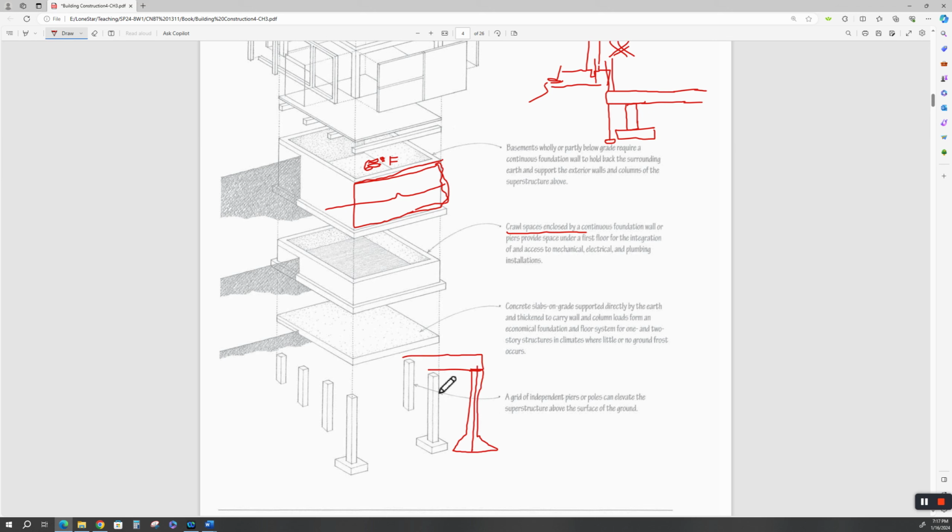They usually use crush boxes, which are core boxes that hold up the wet concrete while it's being poured. And over the life cycle, these things rot out, and if the soil does expand, it expands up into this void space and doesn't affect the slab. And the slab is supported on round piers with a round bell bottom.